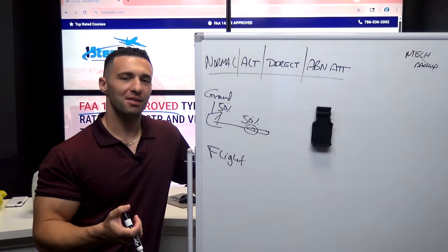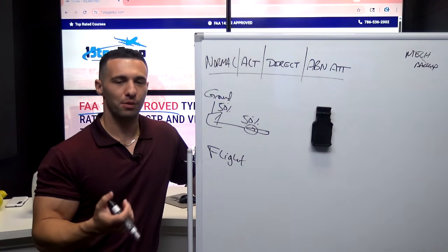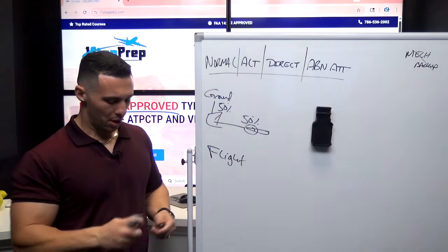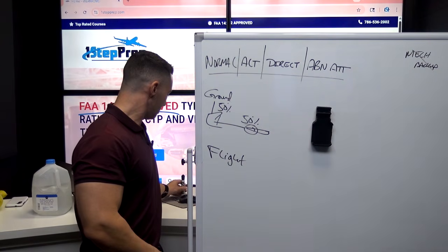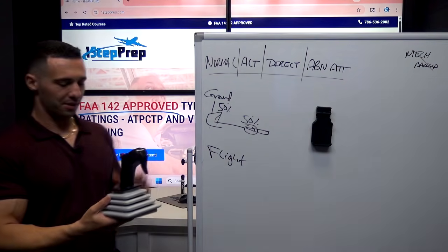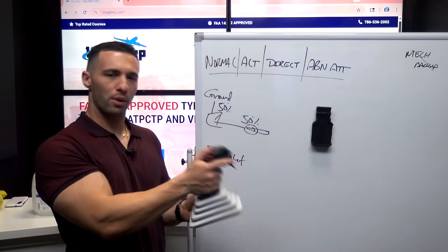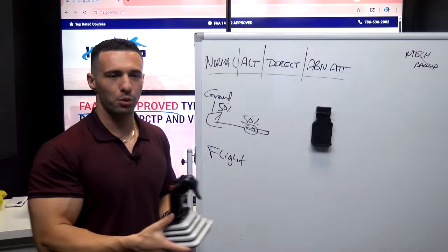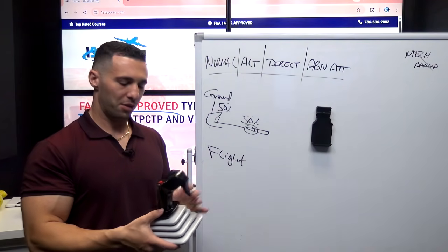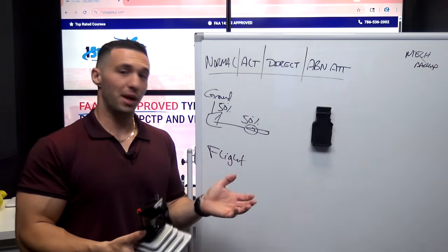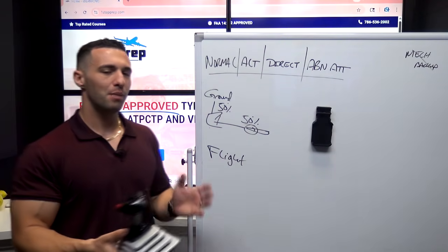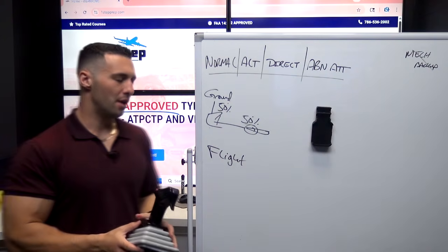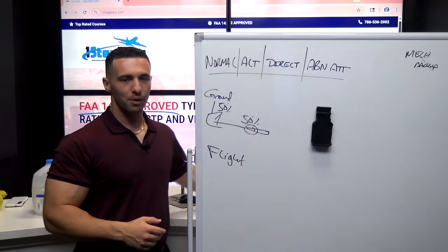I would also like to say on this note that we do have something referred to as the algebraic summing of side stick inputs. What that simply means is that if I'm the pilot flying and I grab the side stick and pull aft, and then the pilot monitoring for whatever reason grabs the side stick and pushes forward, we're basically canceling each other out. And so the sum of that input is 0, and the jet will do nothing. It'll just continue flying straight and level. The same is true if one person goes full left or full right input and the other person goes full opposite input. The sum of both of those, of course, would be 0.